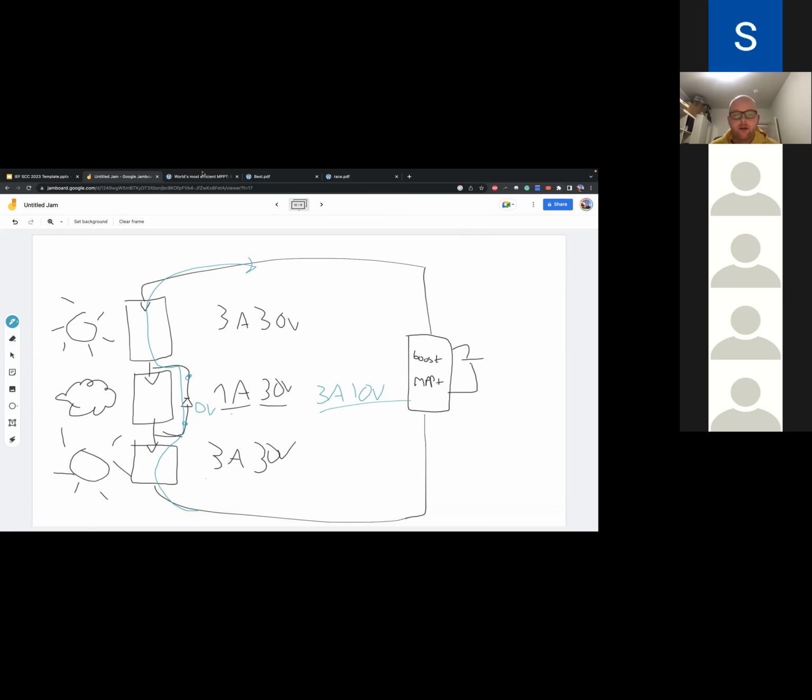But I feel like there are ways to go from this to that, because basically we want to triple the current and decrease the voltage by 3. Well, that's a perfect application for a buck converter. So what I think we should be doing instead of this diode thing, maybe I should make a screenshot of this before messing it up.